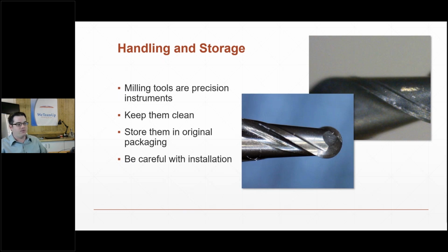And the tungsten carbide, because it's machined to a sharp cutting edge, if it's traumatized in any way that it's not designed to be, it can chip and it can have defects. And if you introduce a defect into the cutting edge of your tool, one way or the other, you'll significantly cut down on the life of that tool.